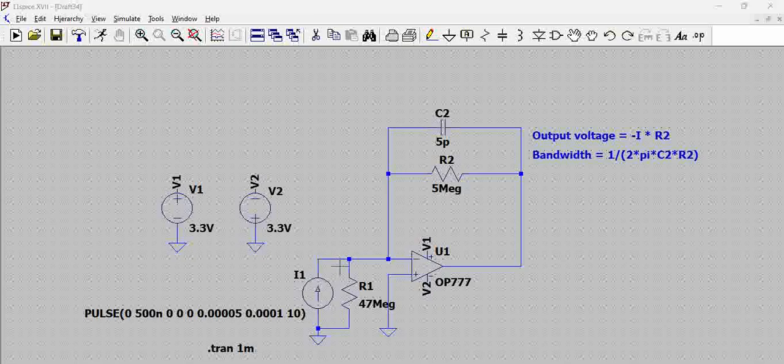Basically, let us assume we have a sensor like a photovoltaic cell, or you can say phototransistor. All these produce a current output based on the sensing that happens, and will be input to this particular circuit. Actually, here if you see, that sensor is modeled by a current source, okay, and this input is further amplified by this particular circuit and transformed into a voltage output, and this can be further given to any microcontroller kind of circuit, which actually converts it into a digital value using the ADC. This is the basic of this particular circuit.